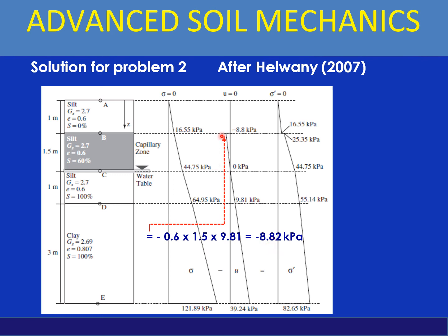The rest of the things are the same. You can draw the remaining part of the pore water pressure distribution diagram and then the effective stress diagram, keeping in mind that the effective stress is equal to total stress minus pore water pressure. So that's all about the in situ stresses and the capillarity. Thank you.